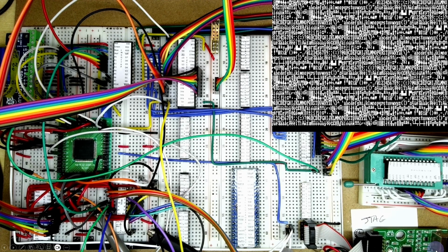Welcome to breadboarding. In the previous video we managed to get our character generator ROM outputting the character set information to the display here. Although at the moment we don't have any video RAM connected up, we're going to be hooking up the video RAM in the next video. But during this video what I'm going to be doing is configuring the PLD here, the complex PLD, so we can output the different attributes. So this will be different foreground and background colours and whether we have blinking video or not.